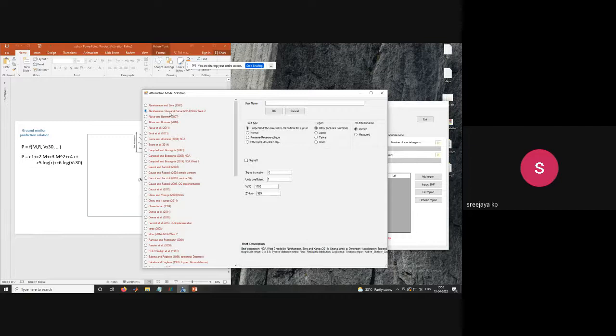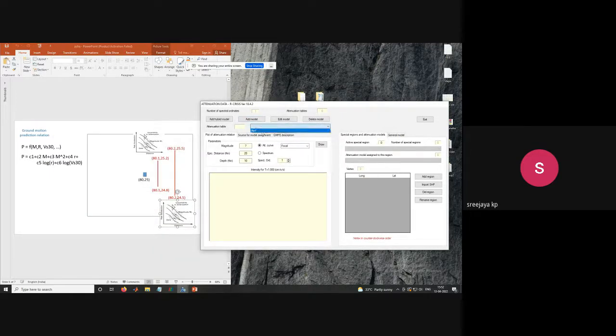So here I am taking two default models. Say, NGA West 1 model. I am giving the name as attenuation 1, and I don't know the fault mechanism, so as of now I'm considering unspecified. And for 760 meters per second, that is for BC type boundary, I am interested to find the hazard. So I have given the VS30 value here. So that's my first model, and you can see the attenuation parameter and property. If you change here, you can draw how the attenuation varies.